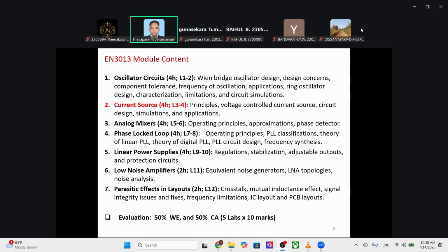So that arrangement is there normally in the testers. Okay, so why is that? You have the facility to separate the supply and sense. The point where you sense it, that is the place the actual set voltage will appear. That feature is there in certain power supplies, depending on the type. Mostly testers use that kind of approach.